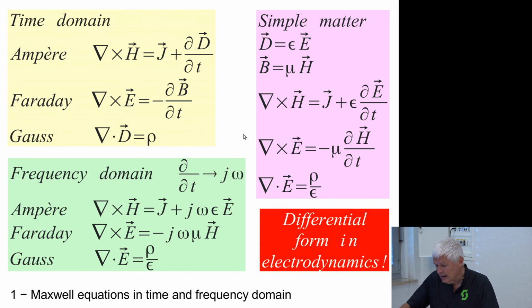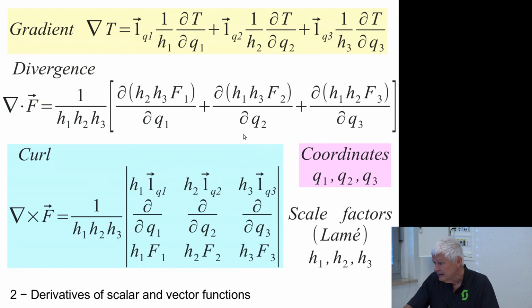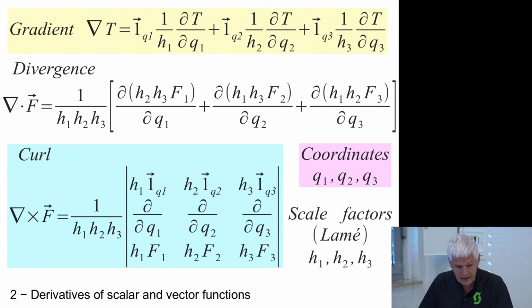Okay, having to calculate all these things, things are simple to calculate as long as we have Cartesian coordinates. What does Cartesian coordinates mean? In the numerical world, Cartesian coordinates means that we have a cubic grid, a square grid in 2 dimensions, a cubic grid in 3 dimensions, where all dimensions behave exactly in the same way.